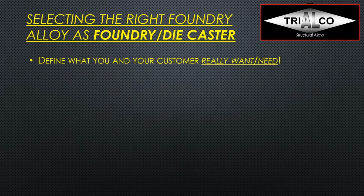So now, what do you want to do if you have to select the right alloy as the foundry, as the die caster? You receive a specification from your OEM, your customer, the casting buyer, hopefully a specification that doesn't just call out one brand name alloy that you can buy from one source in the world, and then on top says that your casting needs to be porosity free, because then you certainly have a problem. And here again, same recommendation: define what you and your customer really want and really need.